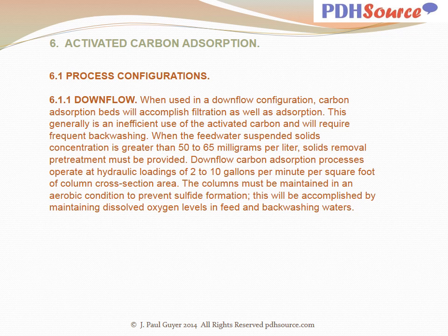With the downflow configuration, carbon adsorption beds will accomplish filtration as well as adsorption. This generally is an inefficient use of the activated carbon and will require frequent backwashing. When the feedwater suspended solids concentration is greater than 50 to 65 milligrams per liter, solids removal pretreatment must be provided.